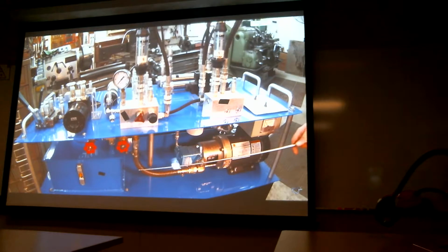And you'll notice that the pump is mounted below the oil level in the tank right here. And that's always the best way to do it because oil has weight to it and it keeps the pump primed whenever the pump is below the oil level. So that's always the preferred method on a pump. All right. So then you move up here to the safety relief valve. And what the safety relief valve does, it protects the system from overpressurization. Okay? So next thing we have is the filters.